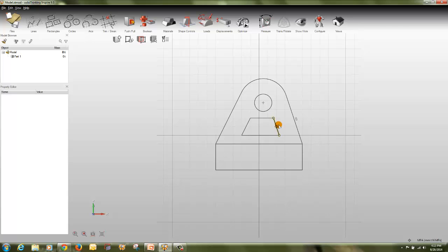It will move in the parallel. It's fixed to the parallel, so wherever you change, it will change parallelly here also. So this you can also make parallel, so it will not change the dimension, it will always move parallel. So it's fixed to this, fixed to this. So you can apply these types of constraints.